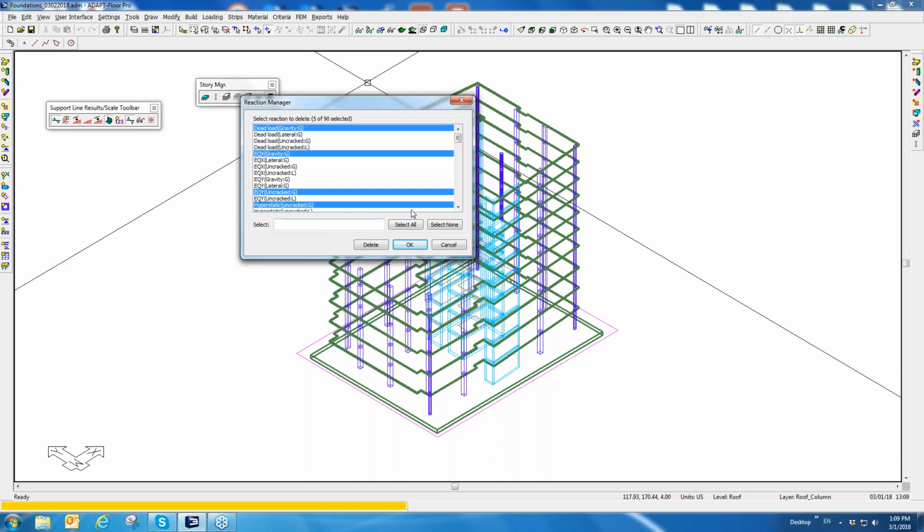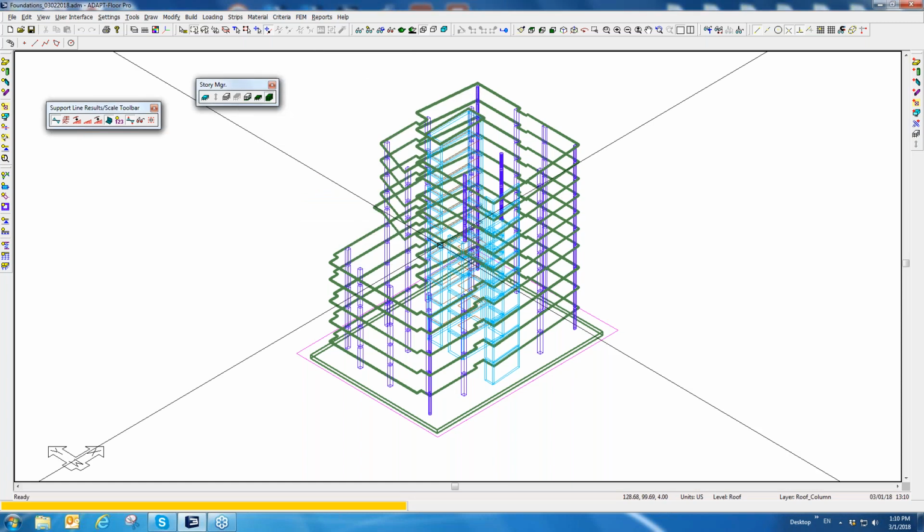And this is showing us that for dead load, we have a gravity reaction made from a global run. That means we ran the model in global mode, full structure, and we used the gravity usage case when we ran the model. So this gives you an accounting of the different reactions that are currently available for you to reapply. And the reapplication of reactions doesn't always need to be at a foundation level or a mat level.